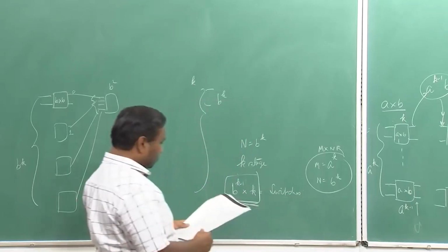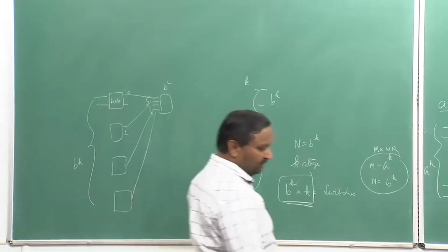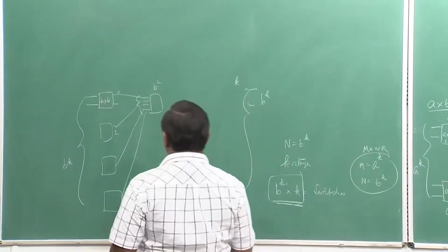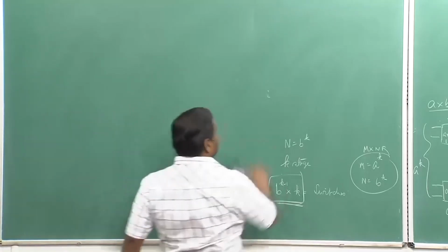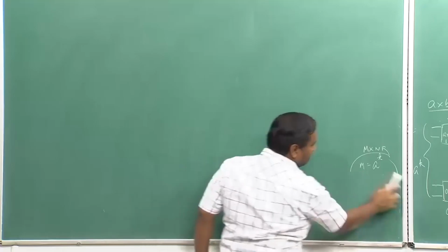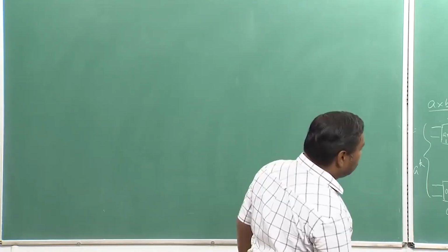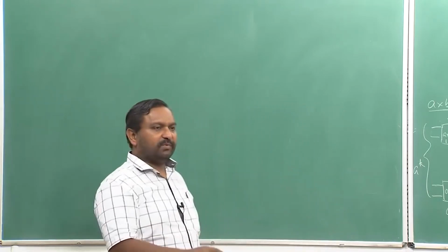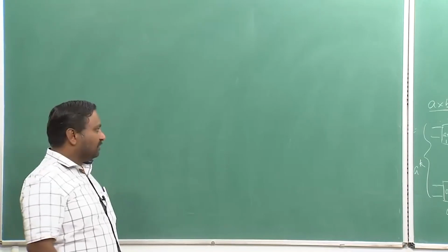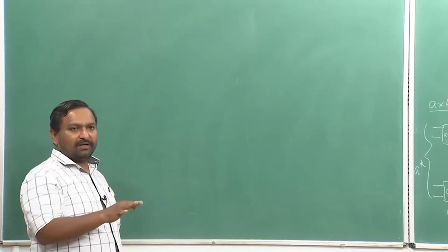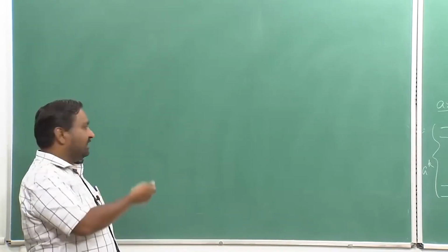And of course, we can actually take few examples and try it out whether self routing happens or does not happen. Only thing, this rule that all the inputs to a switch in a stage should actually come from the same output port level of the previous stage switches should be taken care of, and you will be able to do the self routing. So, the output ports may not be in the order, but those also can always be made in order by actually shuffling the output wires.